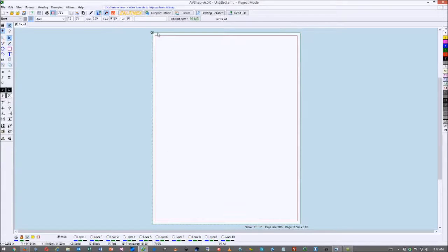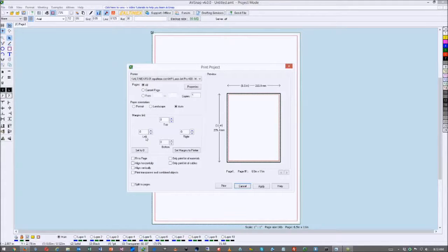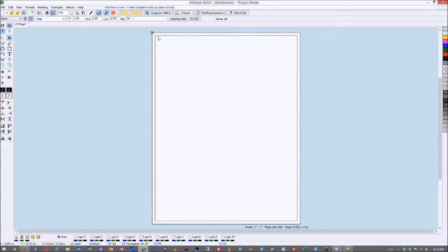So when you do a drawing, make sure to fit to the print area, because the print area is related to the margins of the printer themselves, even though they're not here, but it knows the margins on the printer. So it would be the same as setting the printer margins to 0.17. And you can see now there's a printer margins setting. Okay, so you can go ahead and turn this off.